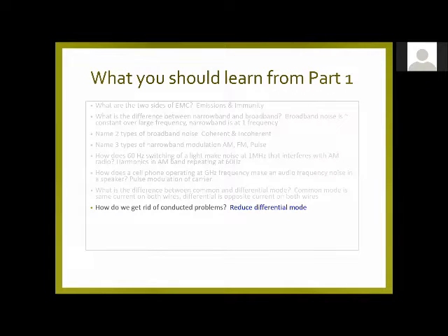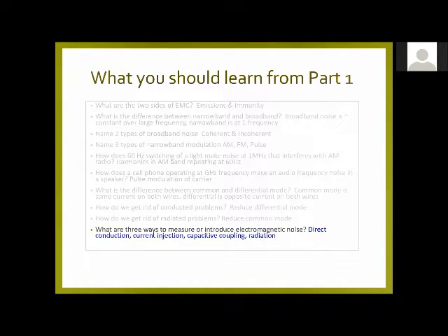Conducted problems, we can reduce the differential mode. Radiated problems, we reduce the common mode. Three ways to measure or introduce electromagnetic noise. We have direct conduction, capacitive coupling, and radiation.